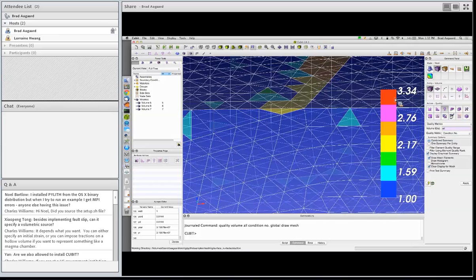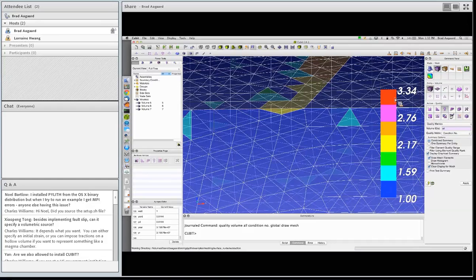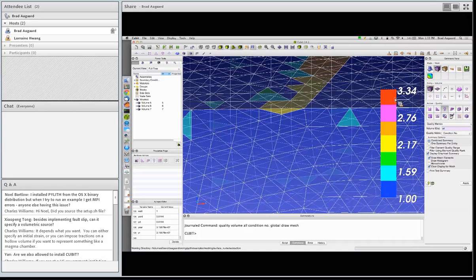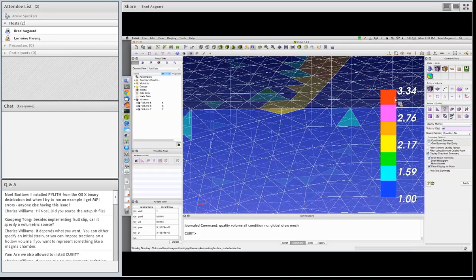But I shouldn't say otherwise, because if you change the geometry, you'd change the solution a little bit as well. So it's really about eliminating the features that are smaller than the resolution of your mesh. You're approximating features smaller than the resolution of your mesh. So how do you choose to do that? Do you want to just live with it and have a slower rate of convergence, or do you want to change the geometry to remove geometric features that are really small to improve the rate of convergence, so you get a faster solution, even if it's not more accurate?